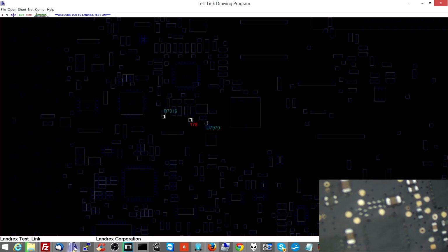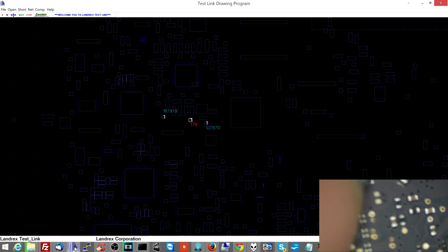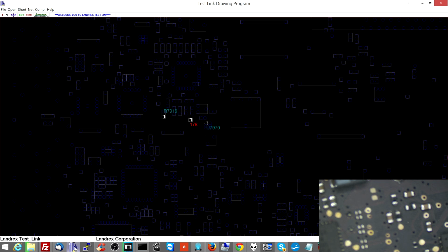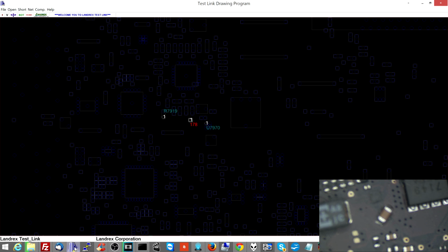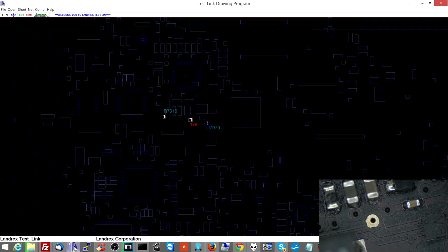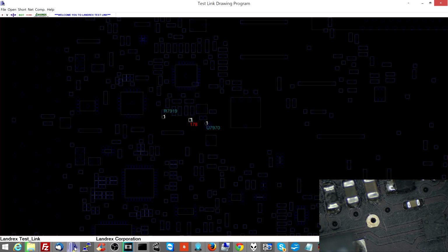Whoever came up with this, I swear. Okay, so let's see, this thing is it. Right by my chip, there we go, that is a probe point. So we're going to measure right over there for the SMC signal. Let's see what we get over there. My God, what a rabbit hole. We get 3.4. So both inputs are going into my logic gate.